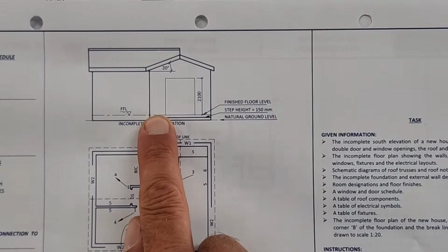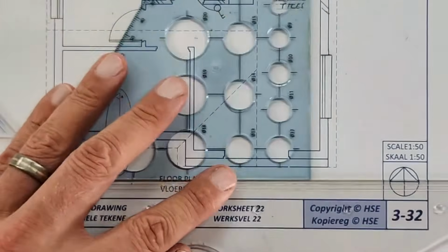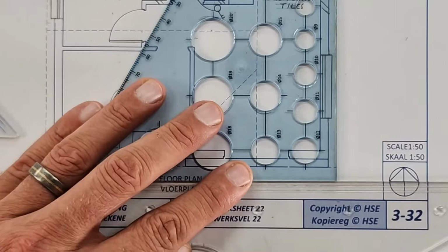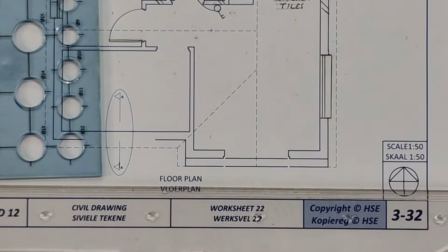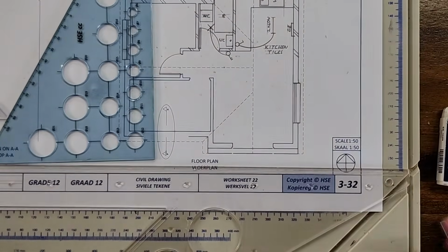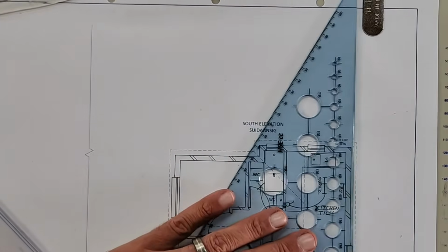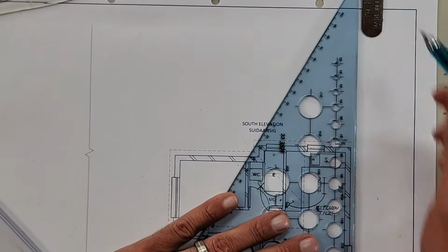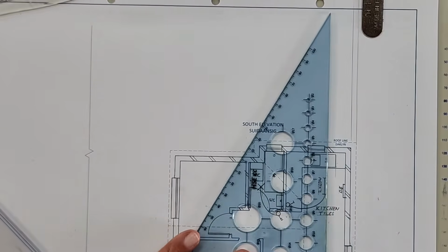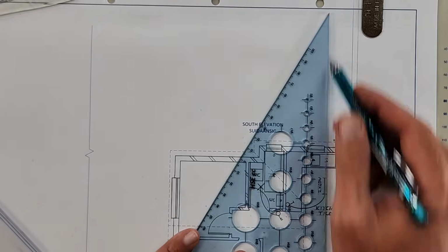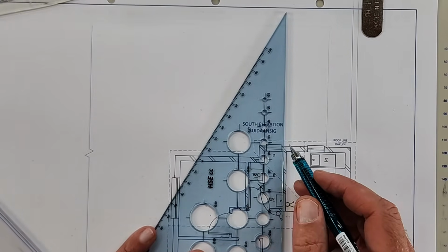I'm going to use some of this information plus what I project up from here. So you're going to just line your triangles up like that. You're starting on the outside of the roof pitch and we're going to project all the way up. Okay, let me zoom out and you can follow with me. We're going to draw there on top. So we start on the outside of our roof overhang, then we've got the outer wall, and now I'm going to do the door frame from the bottom here. You can't see that, but just trust me, I'm doing it from the door frame here, outside of that door